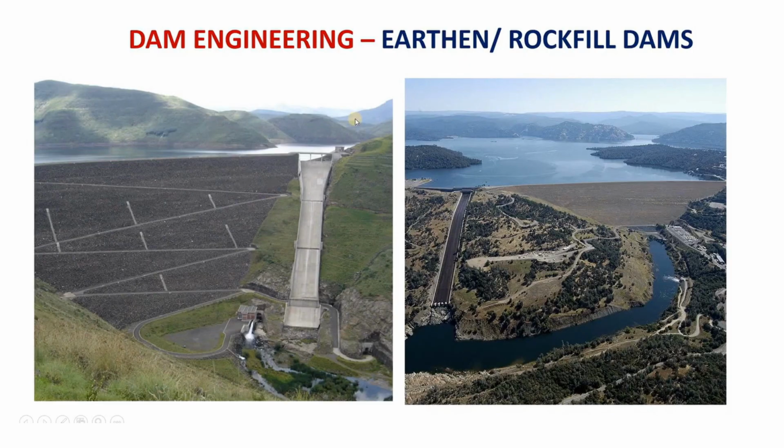Further, a concrete dam requires strong rock as foundation. Whereas, for earthen dams, strong foundation requirement is not mandatory. Further, if the incoming design flood is less, then also we can have an earthen dam type to optimize further. We all know the types of spillways, and the more the incoming design flood, the more is the spillway width.